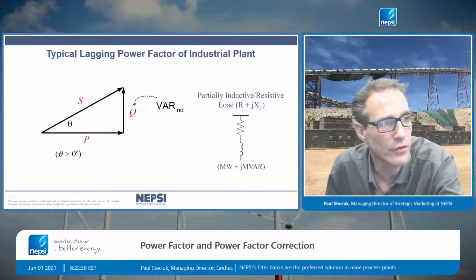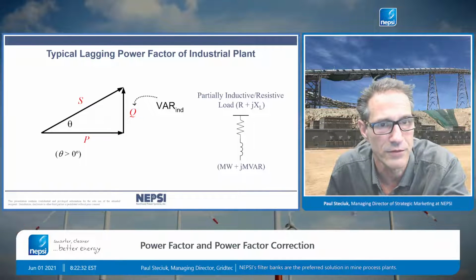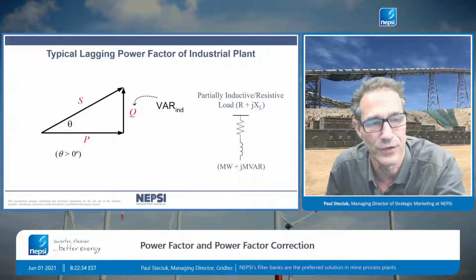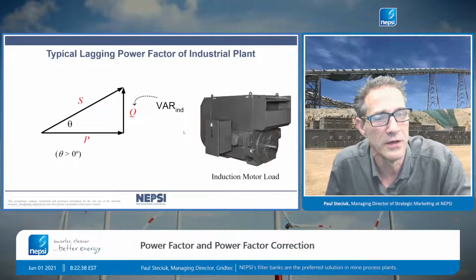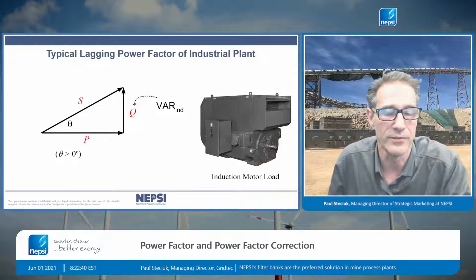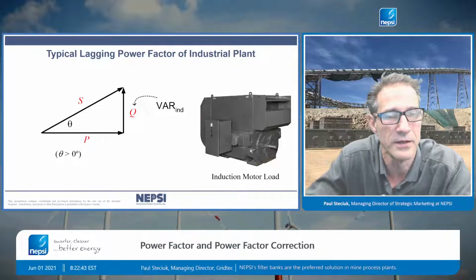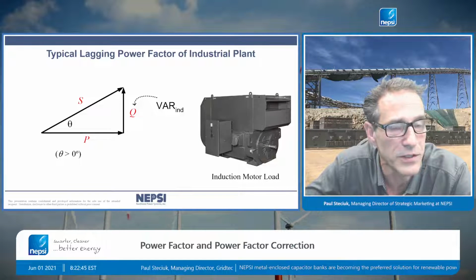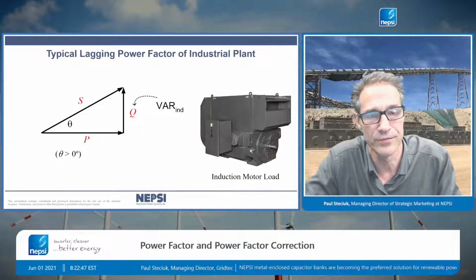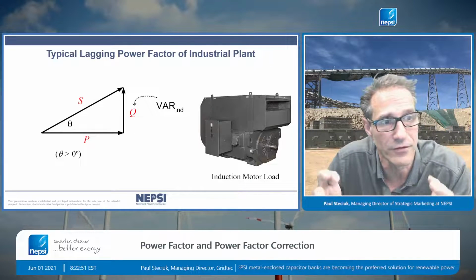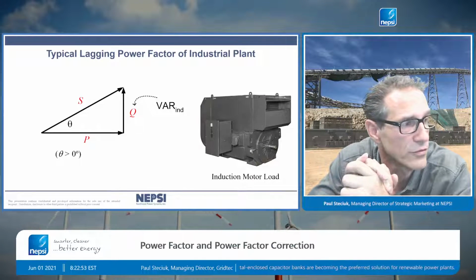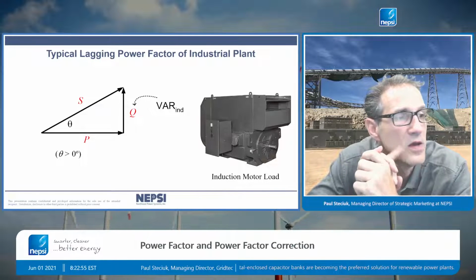A typical industrial load is not purely inductive and is not purely capacitive. The reality is industrial loads consist of things like motors, and motors have a power factor maybe 0.85 or 0.9. You have other variable speed drives which may have a power factor of 0.85 again towards 1.0, depending upon if it's the newer active front end drives, you might have a power factor close to 1.